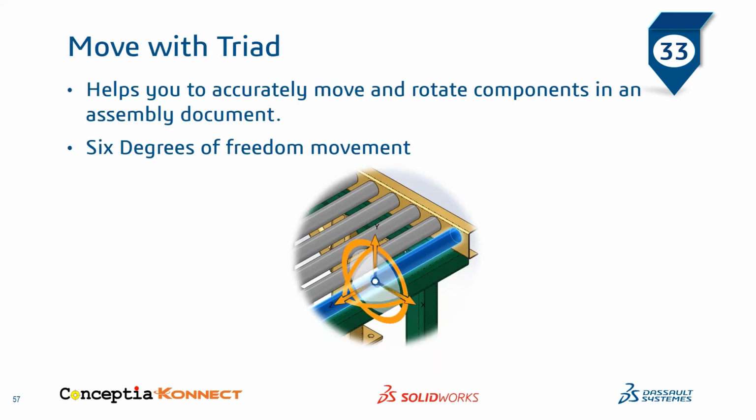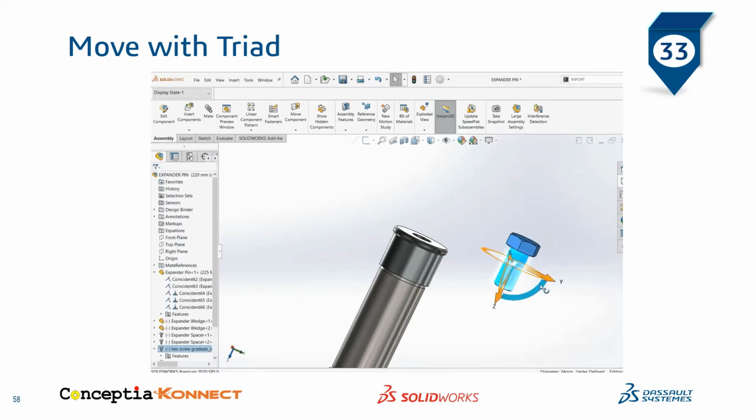Number 33. Move with Triad. This option helps you to accurately move and rotate components in an assembly document, and you gain all 6 degrees of freedom movement while performing this.